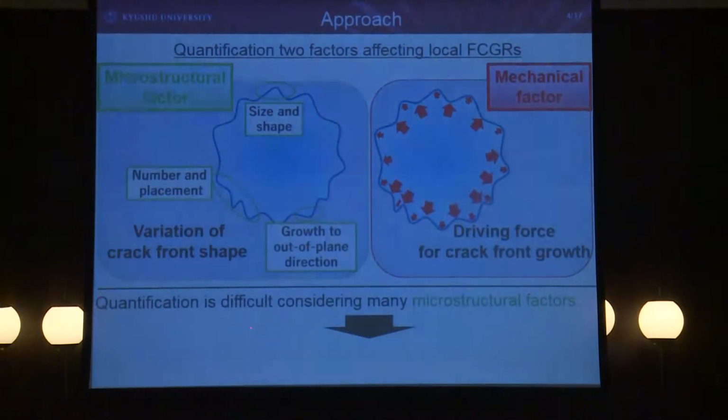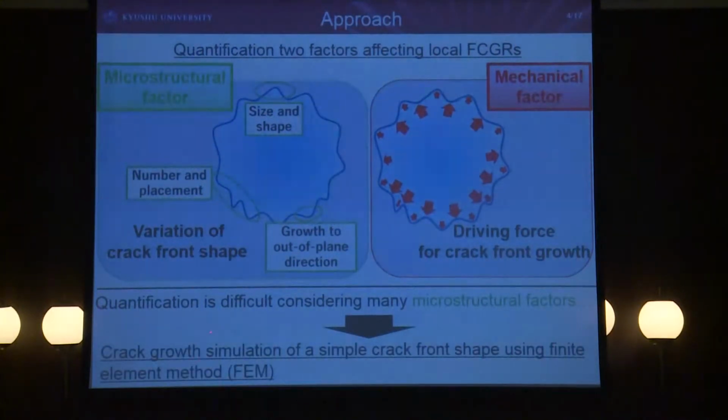Quantification is difficult considering many microstructural factors, so in this study, our approach is crack growth simulation of a simple crack front shape using finite element method. And there are several types of crack front shapes.